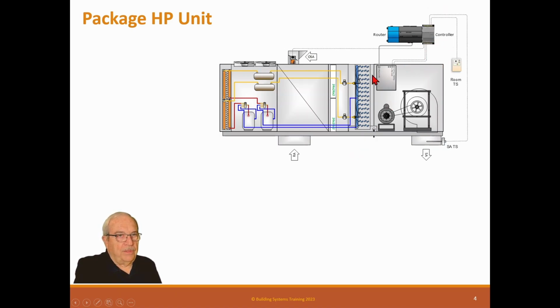The unit has a control panel that's capable of network communication. Not all of them are. So some of them are, some of them aren't. You can put a network control down to it, and now you can see what's going on with the machine. Now you can also, through this network controller, program start-stop points and things like that within the unit, when you want it occupied, non-occupied.